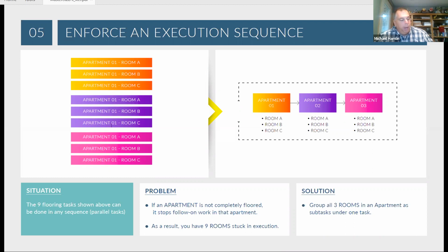And so my tile crews, they would want to move from bathroom to bathroom to bathroom. Then they'd want to come back and do all the tile in the kitchens. Then they'd come back and want to do all the tile, let's say, in the entryway. Those are my 3 rooms. However, until all the tile is done, I can't have my other trades come in, right? They can't be walking across the floor. They can't be putting cabinets in. They can't be doing finishing on the walls or electrical or anything like this, right? So again, while the tile folks are very busy, all my other trades are sitting and waiting. They're waiting for them to get completely done.